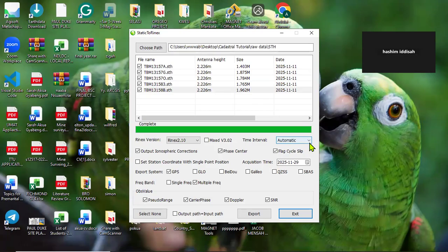What if you are given projected coordinates and you didn't get your points from the site? They're just projected coordinates and you want to use them to prepare a site plan. In that case, you just go straight to AutoCAD and then you plot. You don't need to come here. This is when you pick raw data from the field using your GPS or your GNSS receiver.